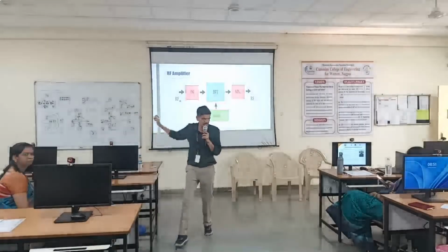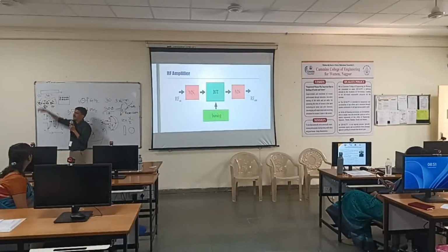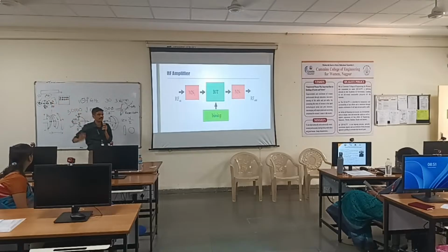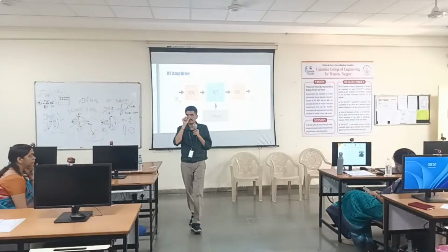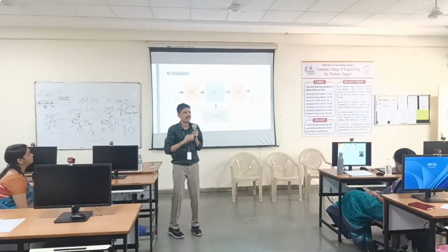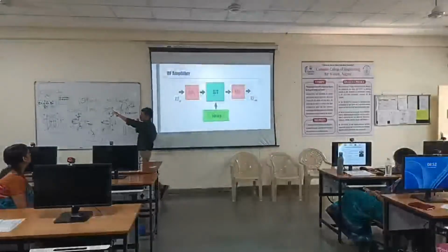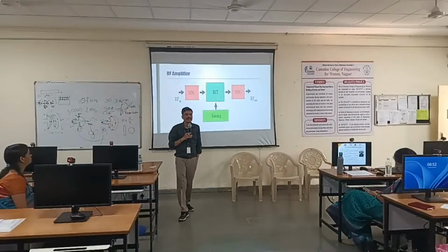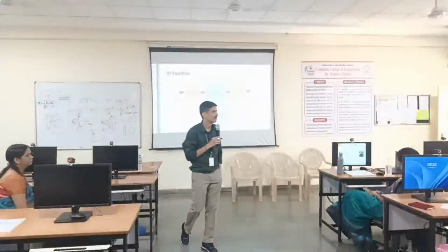Does this design equation depend on frequency? No, it is not dependent on frequency. You can do it at any lambda. Okay, so your job is done. You just have to design these networks. One type of matching network I have shown here. So your amplifier design will be finished here.